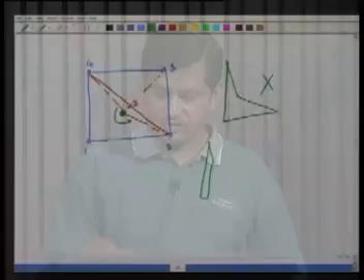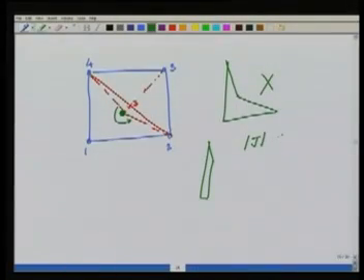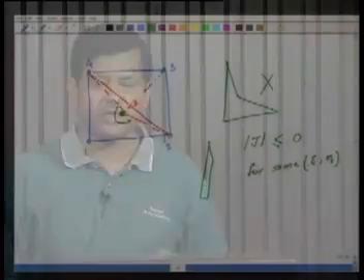So while making the mesh, we have to ensure that the quadrilaterals are as good as possible, with angles not too large and not too small. Otherwise we will have a point where the Jacobian is less than or equal to 0 for some psi and eta. This is a very important point to keep in mind when using quadrilateral elements.